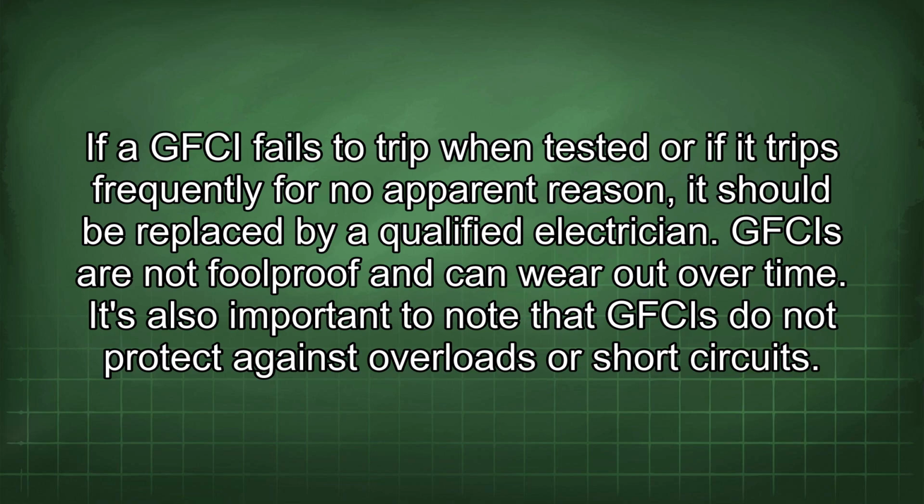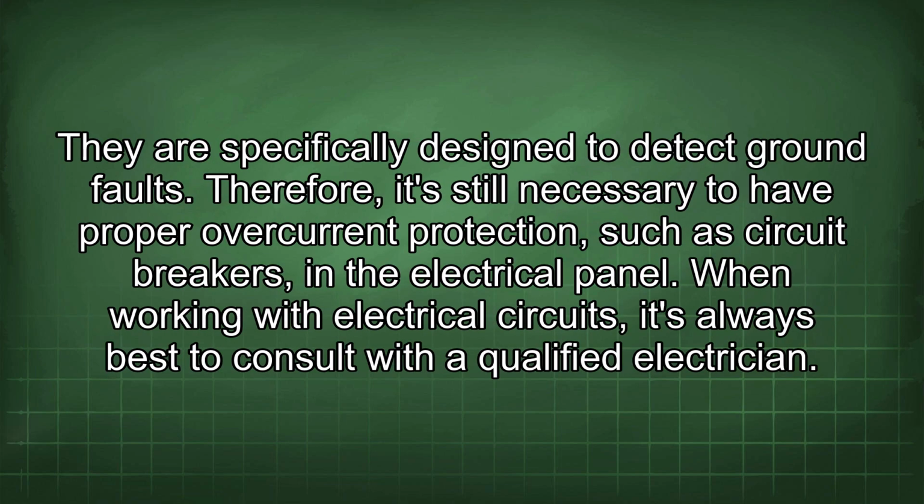It's also important to note that GFCIs do not protect against overloads or short circuits. They are specifically designed to detect ground faults. Therefore, it's still necessary to have proper overcurrent protection, such as circuit breakers, in the electrical panel.